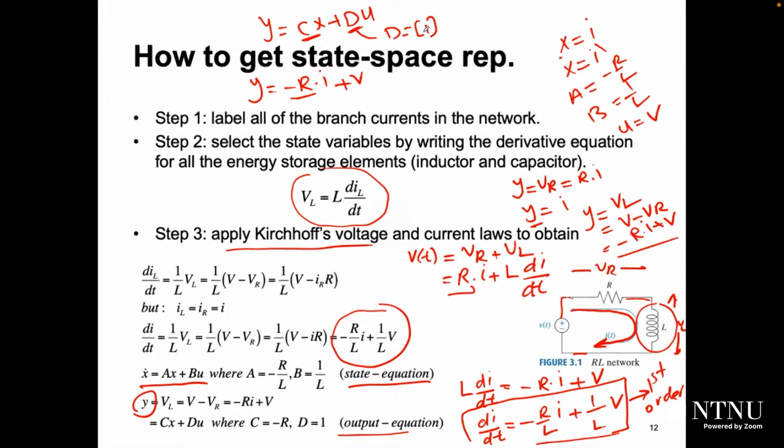So the most important thing in state space representation is the state equation, and the output equation is something which you need to select, right? Because you have a motor, for example, and one person would like to control the speed. So the output equation for him will be speed, because I need to measure speed. For someone else who wants to measure position, I will measure position.